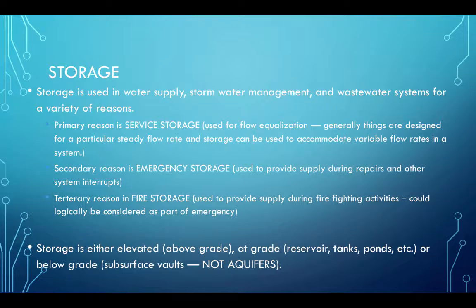We might actually get to witness some of that in the upcoming hurricane that's going to hit the eastern coast of the United States in a few days. In those cases, the purpose of emergency storage will be when they lose electricity. At the very least, they can keep the system somewhat pressurized to prevent contamination from getting into the system during restoration of services.